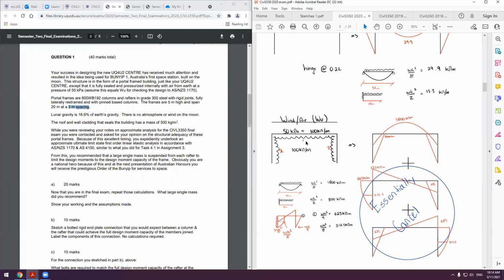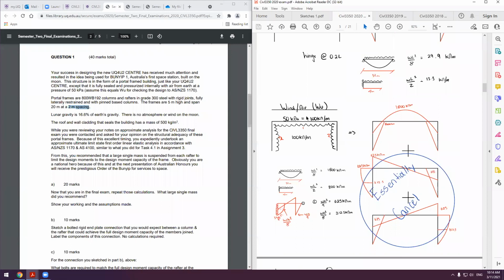I break this down into our force on the one column each, and then the force on the beam at the top. And the first thing I always do is do your beam at the top, because that's your simplified method that you've already done 2 previous times for your dead load, which creates this. And then we essentially have these 2 column loads. They essentially cancel each other out, which is really good when you're under time pressure. So I wouldn't even bother calculating your moments due to this internal pressure on your 2 columns. It's just a waste of time. However, I wanted to do it to show you that they are the same. So we've got 625 on both sides in opposite reactions.